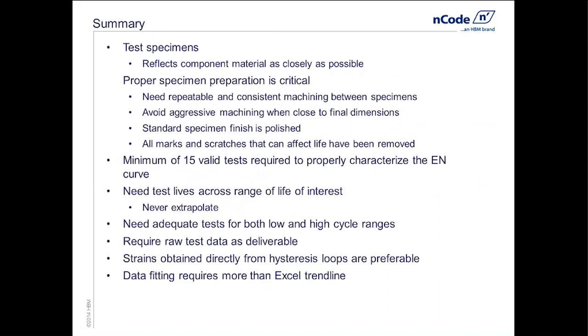So with the cyclically stable stress-strain curve and the strain-life curve, we now have enough data to go off and do a crack initiation fatigue analysis. So in summary, let's walk through the steps we've talked about, the things that we had to at least answer questions on for the test lab, or for our internal test lab at a company, things that we need to worry about.